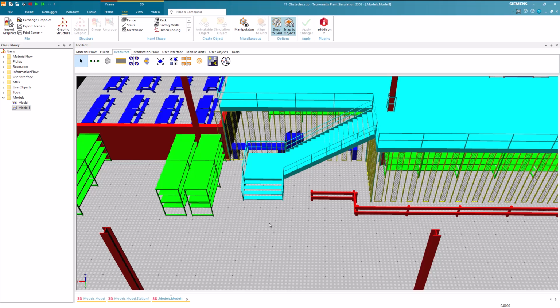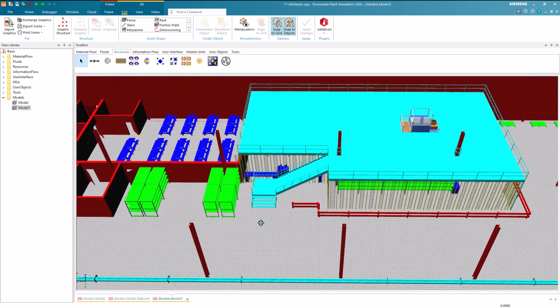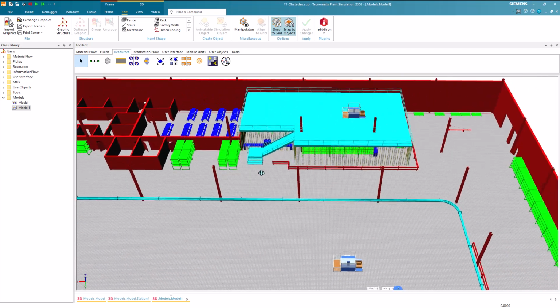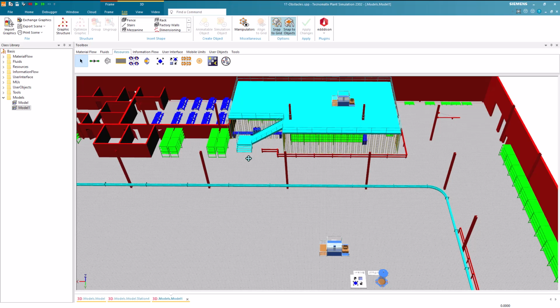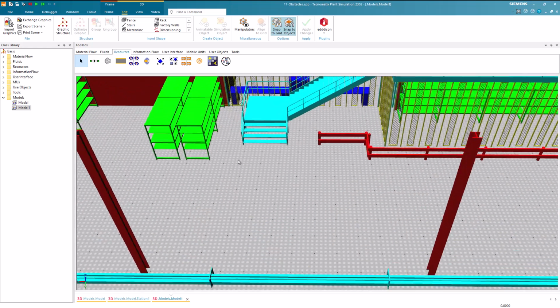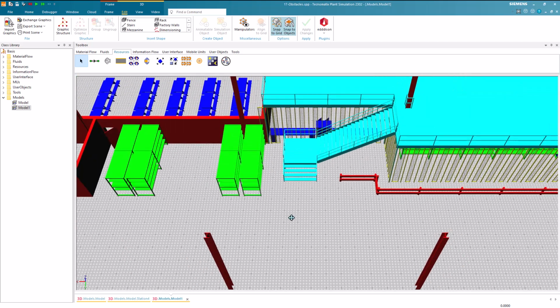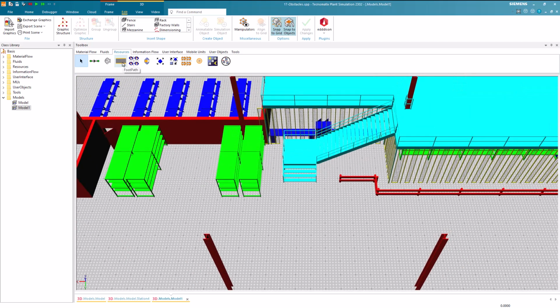So now we have 2 options. Either we insert a stair that rises to the level of the workplace, or we use a footpath. To use a stair can be redundant since we have already a graphic of stairs. Therefore, we use a footpath. Here we should now take care that the footpath starts before the obstacle, so the worker is able to walk along them.